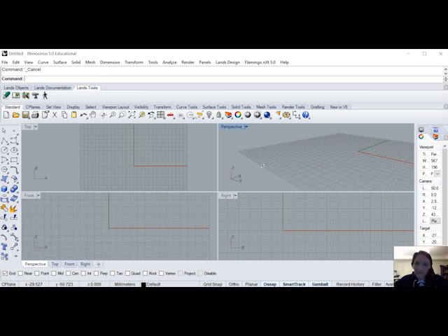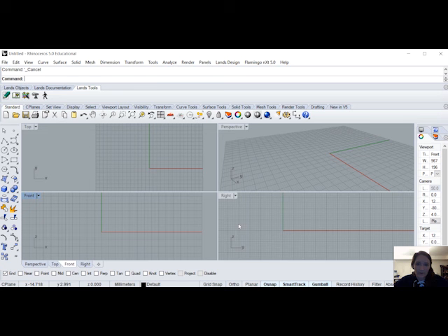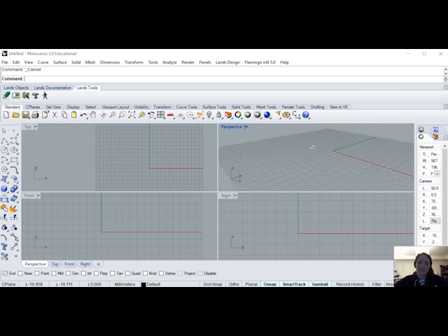If you want the same kind of effect in your perspective world, hold down Shift and the right key, and then you can pan in perspective. And now, this is a good bit, if you press Shift and the right key in any of these three, nothing happens. Don't worry about it, unless you want to. You can do it. This is with Shift, this is without Shift. No difference. And that works for all of them. Your perspective is the only one that will change. That's obviously because it needs more functions to be able to work.